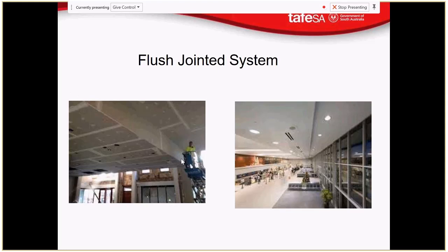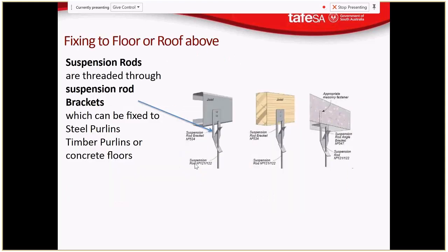Levels of finish differ between applications, where in the building it's applied, or what type of surface finish is going on there, and also there is consideration given to lighting, etc. So if we have bright lighting which is perpendicular to the surface, then far more attention to detail needs to be made in regards to the jointing, because any imperfection will show up very well.